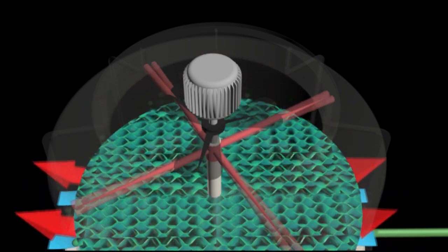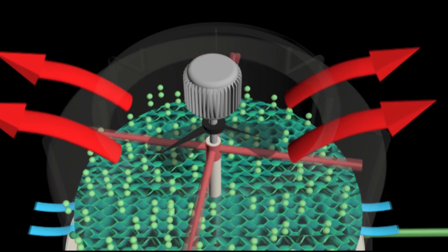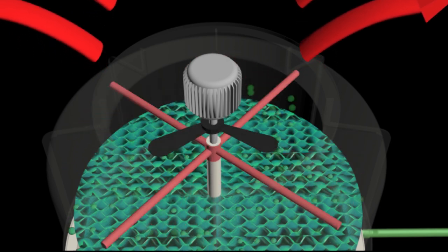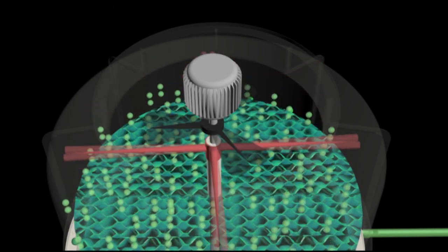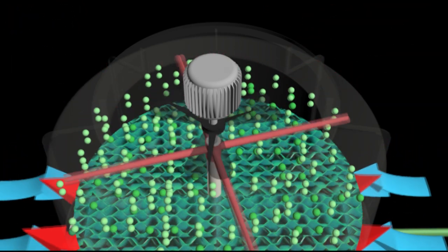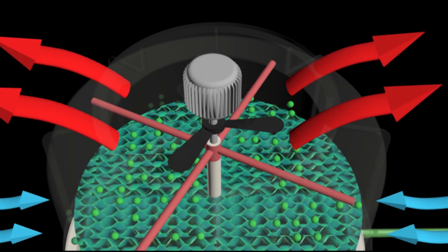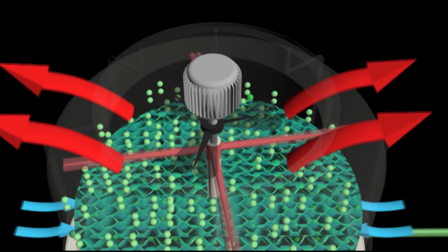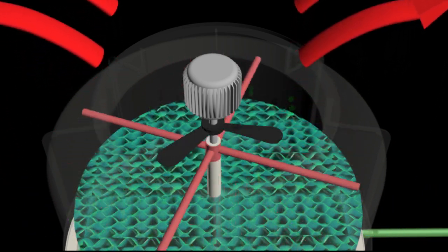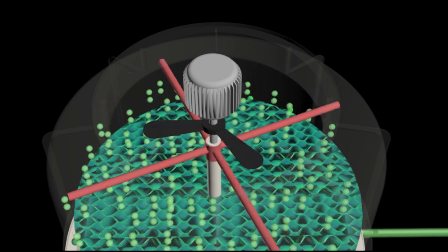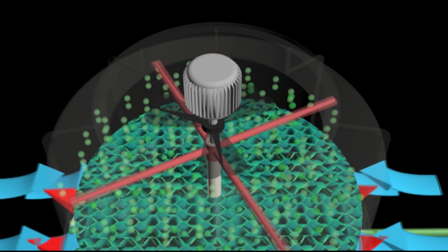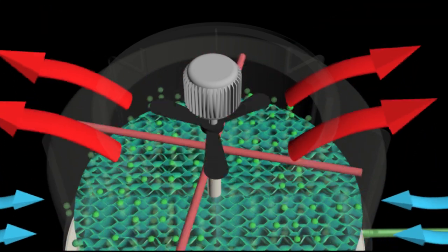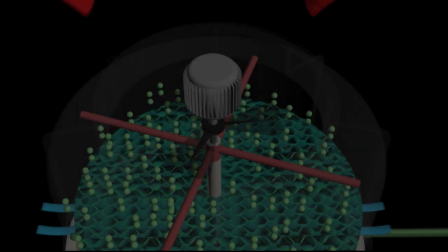This can delay the time and the heat can be absorbed more effectively by the surrounding air that is passing through the fins. Air through the fins is forced by a rotating fan on the sprinkler blade rotated by the motor. This fan rotates with its gusts upward. This will cause the air to move from the bottom to the top of the cooling tower, which is opposite to the flow of the condenser water.